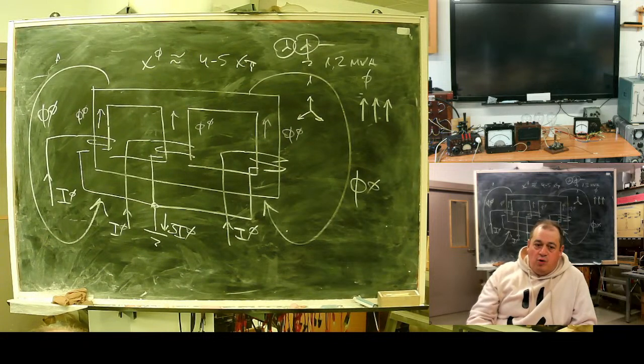One more problem: if you have high presence of third harmonics, expect possible nighttime overvoltage. It's because of transformer core saturation.